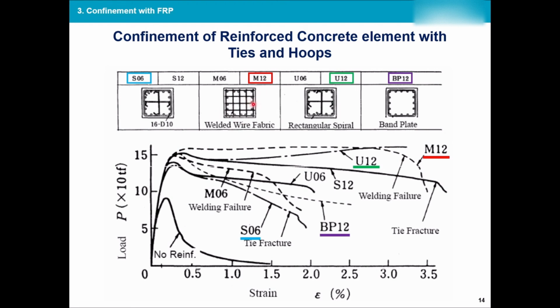So for sure, having lots of reinforcement over there is good, but remember, there's always a ratio. Too many of these reinforcements means that less concrete will be in the middle. Remember, the steel is there to improve the tensile strength of the section. If you have too little concrete, then your compressive strength will be reduced, which can cause much more problems than the tensile bits. And on the other side, making such a thing takes a long time and is very labor intensive, as well as you buy steel in terms of tonnage, how you weigh the steel. So the more steel you have, the more expensive it will be. So the cost is an issue as well.